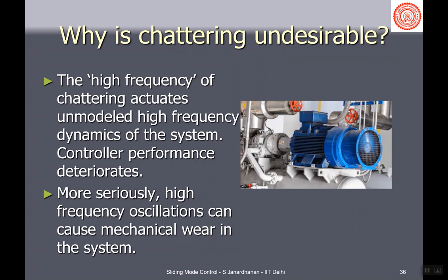If you have a physical system and you are using a sliding mode controller, and the system by chance has quite a few mechanical components in it, you will end up actuating the high frequency modes of that particular system, which are usually not considered in the models. So they are unmodeled high frequency dynamics in the system. The controller performance degrades, and more seriously, the high frequency can cause mechanical wear in the system.